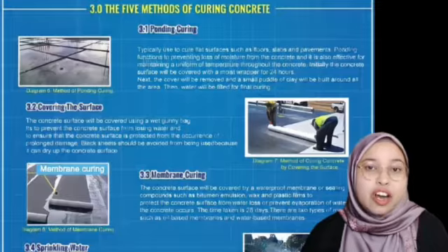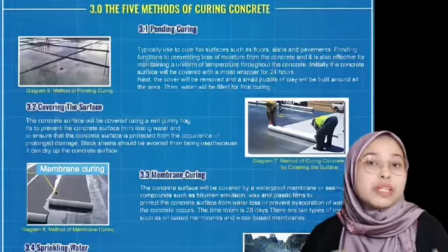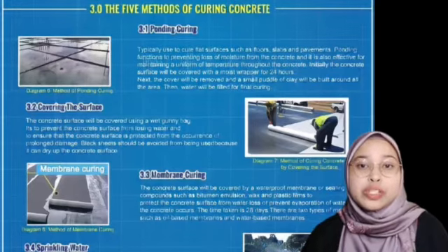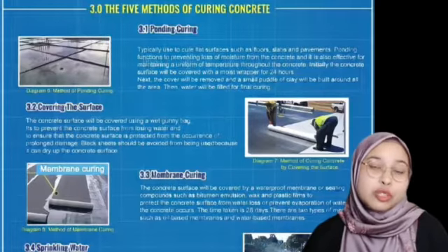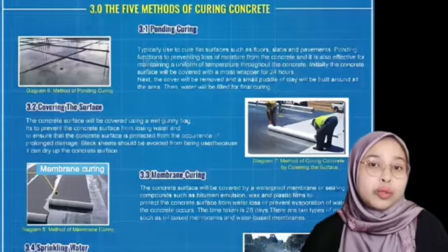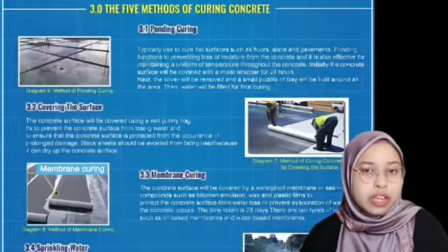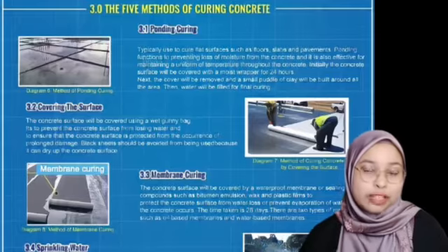The selection of the cover used to cover the concrete surface should be correct. Black sheet should be avoided in covering the concrete surface as it has the potential to diffuse heat more quickly and make the surface warmer. As a result, the concrete surface will easily dry and lose water.